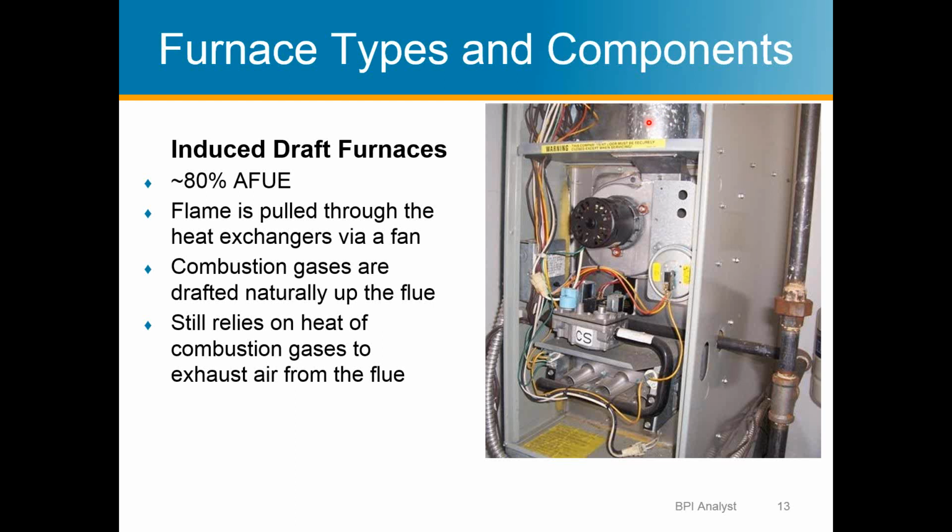What that allows is it allows this vent pipe, you don't need a perfect airtight seal on it, because if there's a small leak in this vent pipe, it's just going to suck fresh air in. Of course, you don't want too many holes, but small holes are fine, or just seams that aren't sealed perfectly, because the pressure inside is negative.